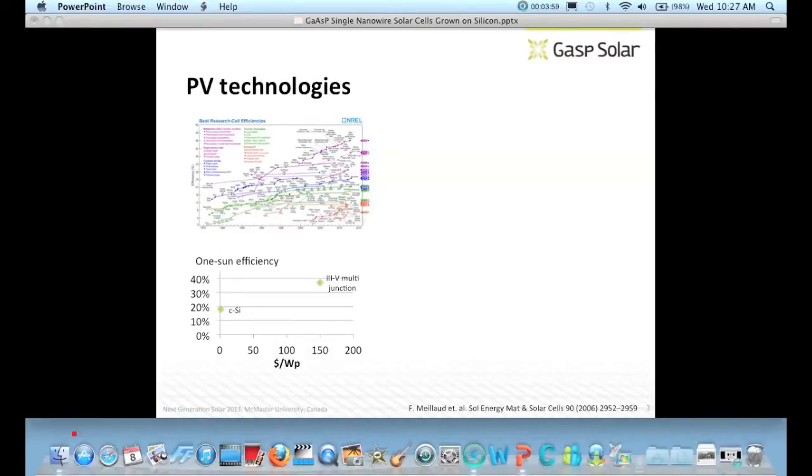The huge gap in cost between monocrystalline silicon and multi-junction III-V leaves space for a market here, because we know that the market demands solar cells which have a high efficiency but a lower cost. Right now, for products like portable consumer electronics, CPV and auxiliary power supplies, these cells are either too inefficient or too expensive, or too sensitive to the spectral distribution of the lighting in the room. So even if you covered your iPad with these III-V multi-junction solar cells, the efficiency in this room wouldn't be very much, because the different junctions will not be current matched. So you need a high efficiency cell at a lower cost.